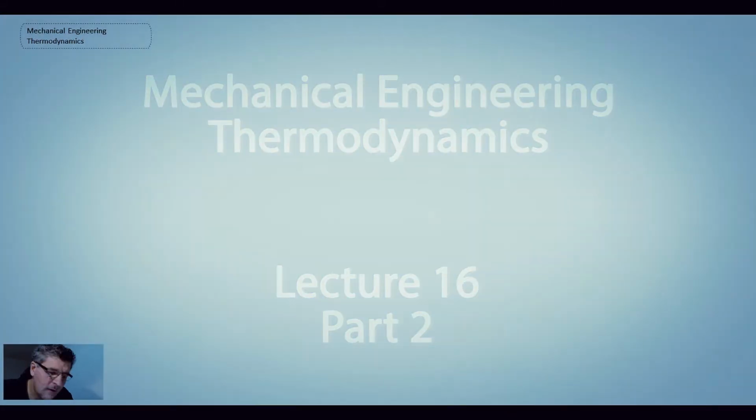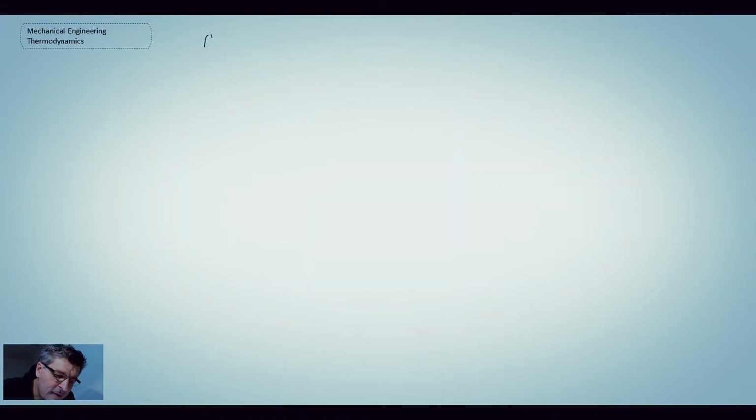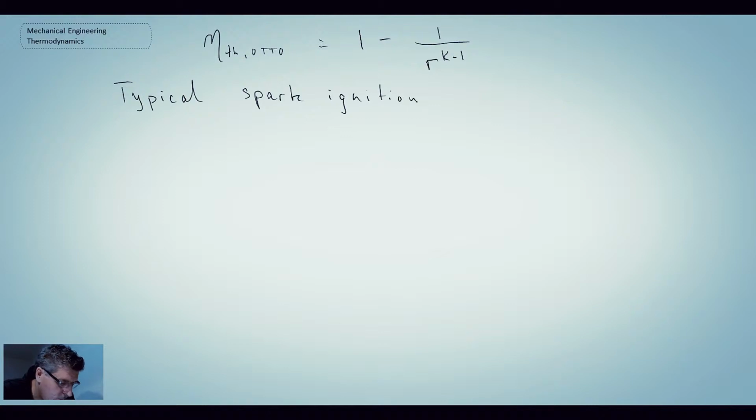So we just came up with an equation for the thermal efficiency of the Otto cycle. And we said that it could be expressed in a compact manner in terms of the compression ratio and the ratio of specific heats. Now, typical spark ignition engines, sometimes you'll see that referred to as SI for spark ignition, have compression ratios that range from about 6 to 12.